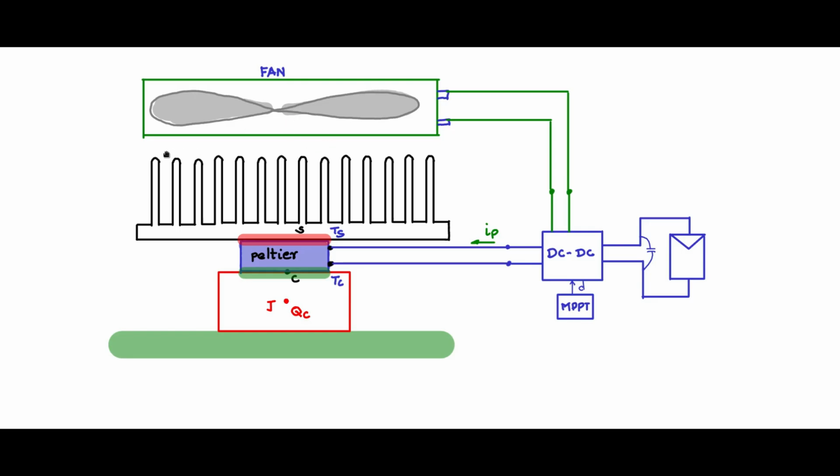It will enable flow of air through the fins of the heatsink and remove the heat at a much more rapid pace. The fan together with the heatsink will have a thermal resistance R theta sink to ambient, which is much lower than just the plain heatsink. Therefore, for a given sized heatsink, forced air cooling will lead to much faster heat flow through the heatsink.